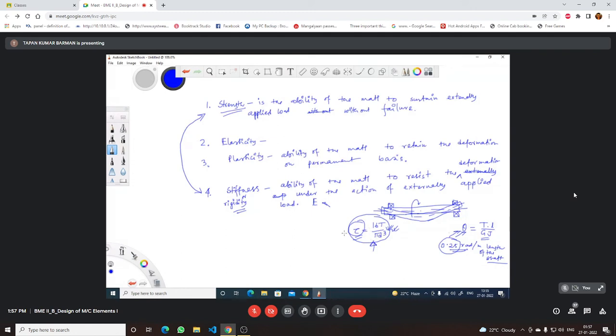If you consider these two different equations, your dimensions will be different. When we discuss the design procedure of shaft, at that time we will consider these methods, not two, three methods to make the design of shaft. One should be based on strength, one should be based on rigidity, one should be based on code.